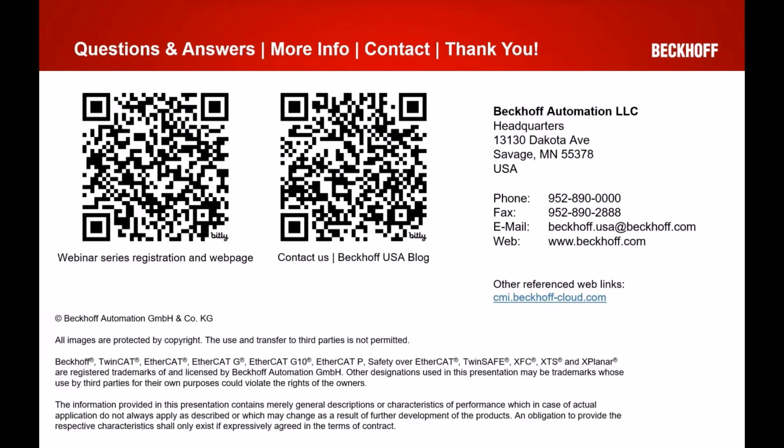All right, the first one we have is: is TwinCAT HMI included with the base runtime, or is it an additional module like the PLC HMI? So the difference between PLC HMI and TwinCAT HMI is a lot of what we talked about. TwinCAT HMI is a little bit more standalone. So it is not necessarily included in the base runtime. You'd have to install it separately. You'd have to install the server component, and then your client can be anything with a web browser. But yes, it's an additional TF package, as we like to call them, an additional installation and an additional license to run that server.